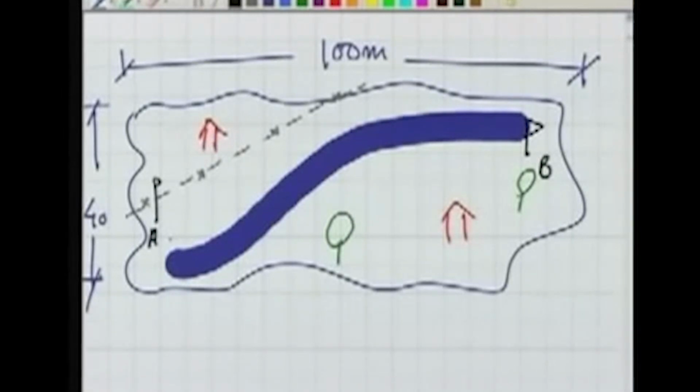Now there could be an imaginary line between these 2 points. Let me draw the line by red color. There is no physical line in the ground, but this line is marked with the presence of these 2 ranging rods. So job number 1, when we are going to the field, is reconnaissance, locating these 2 points A and B, where these points could be.